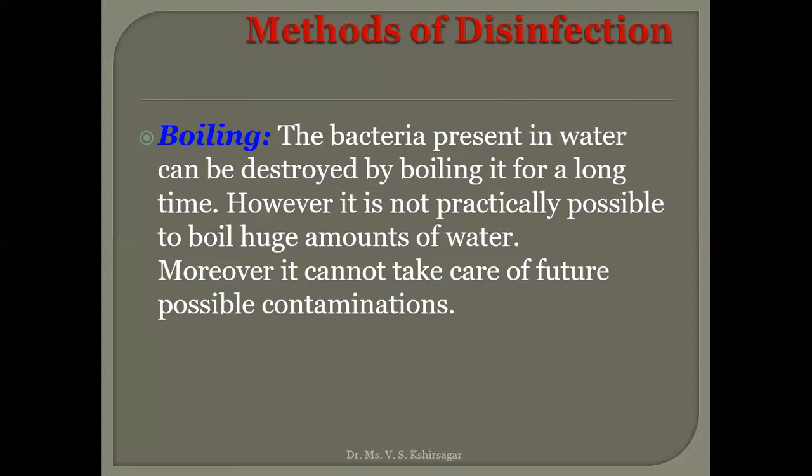In disinfection, there are different methods. The first and very popular one is boiling. But it is possible to use this method at the individual level, because is it possible to boil the entire quantity of water which we are going to provide to Pandharpur city? No, it is not possible. So the boiling method of disinfection is applicable only at the individual level.